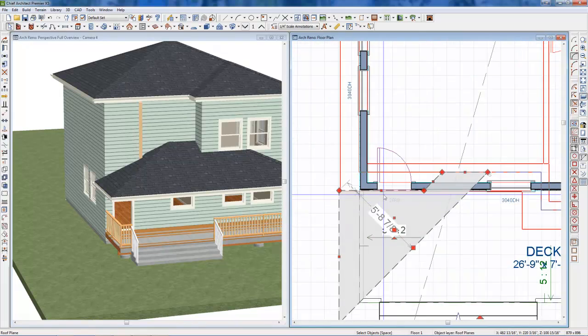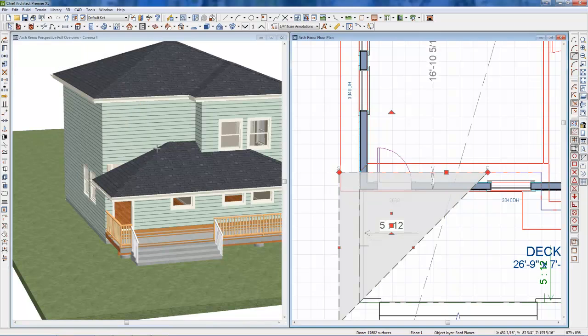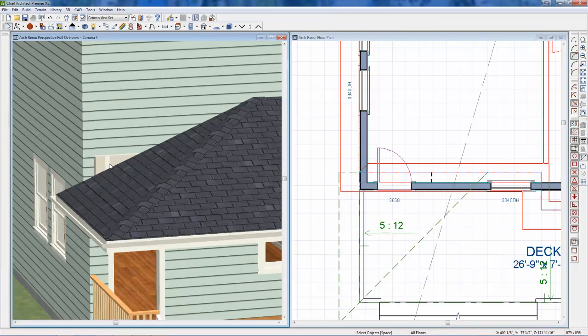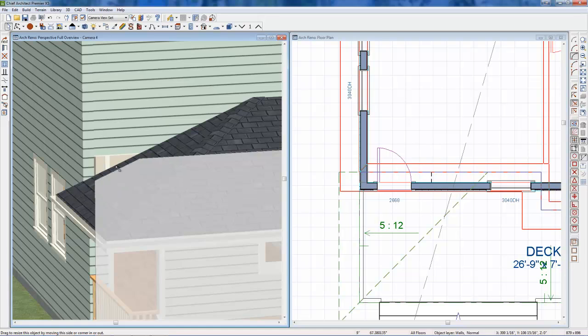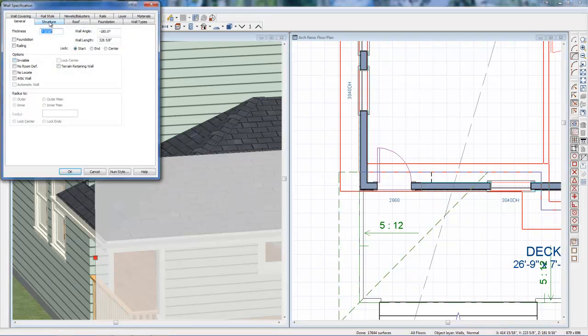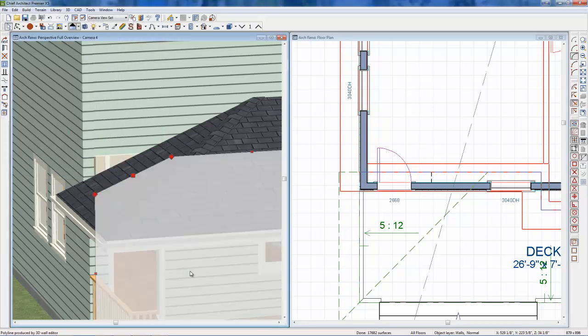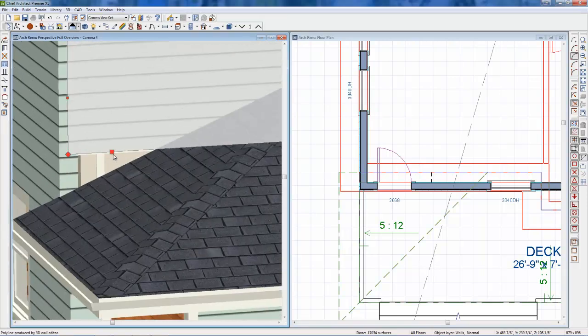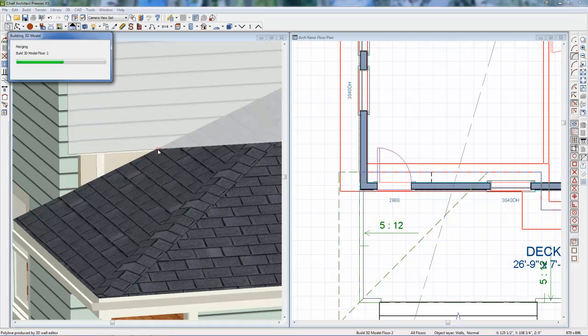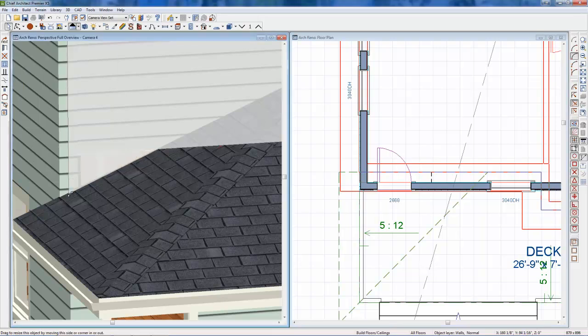So the best way to do that is to have the roof itself go back and cut through the wall. That would be better. Okay, that's good. And we notice that there is a little gap there. Oh, what is that, a door that I captured? There's a little gap there on the wall because of what's going on here. I see. So that's building there. So let's go back, and structural will say default wall. So what happened was that wall was cutting through where it's supposed to cut through, and this one doesn't want to build per se any lower because of the fact that it is not there.